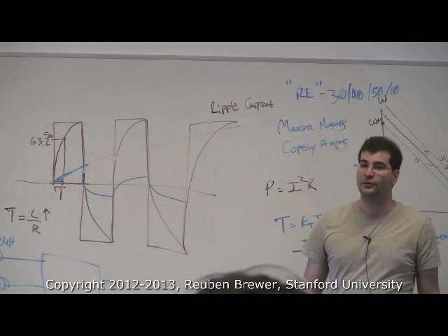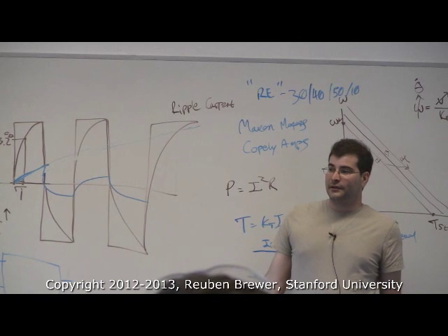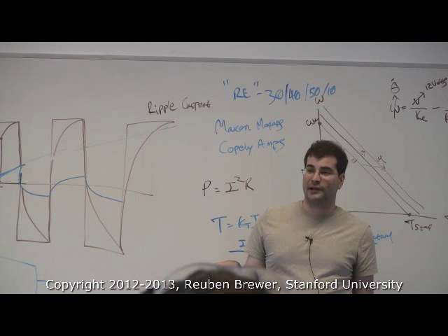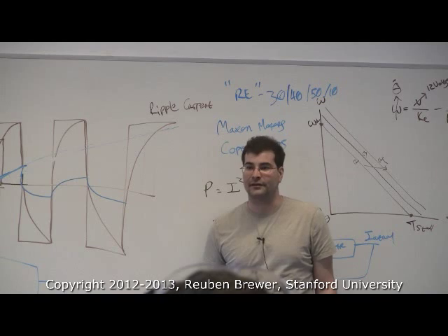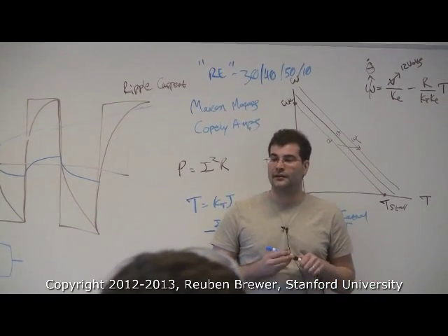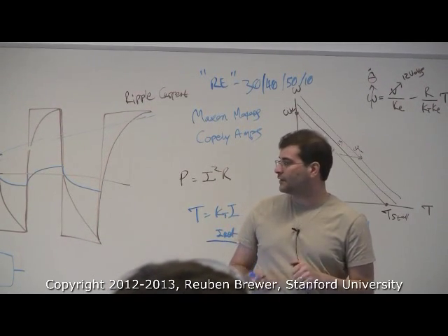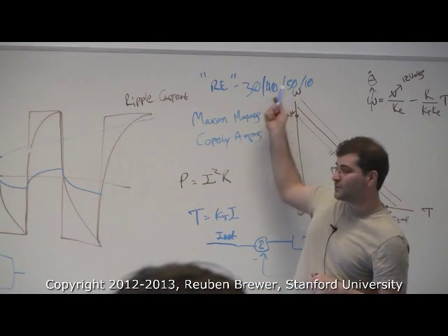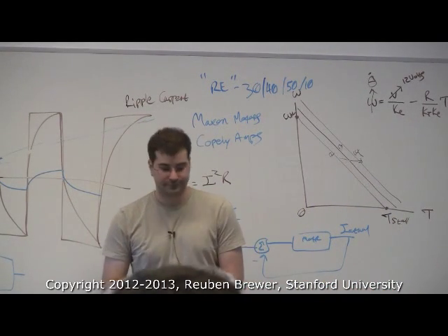So what you want to do is be real careful when you plug in a Maxon motor to a Copley amp, and have your finger and thumb on it as you're starting it up to make sure you're not torching it. And if you really want to understand this stuff well, there's a guy named Dean Crumlish at Copley, who's an expert at this. They will not connect you to him. Don't try. Somehow get his number, call him directly. He's super nice. And he will tell you all of this, and has. But remember, RE10, the smaller equals smaller wire, higher resistance, lower tau, higher ripple current, torch.